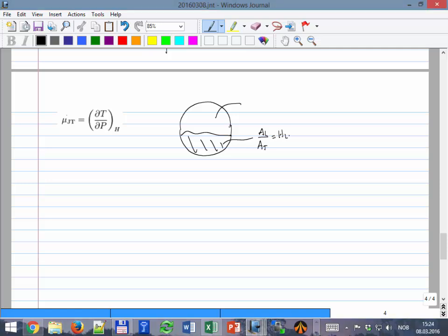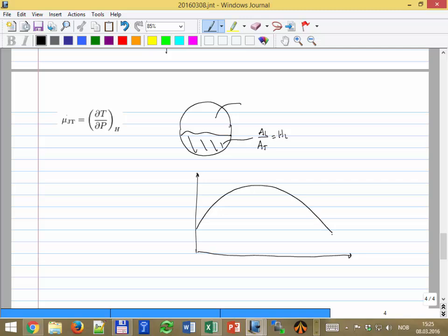So if it's increasing, if it's doing that behavior, it's doing something like this, what could it be indicating? We leave it for the homework, and then you have to explain. You will have to explain anyhow, so better to do it in class. Why might the hold up be increasing? Condensation. Okay, that's one thing. I just have more liquid, and there is liquid coming out of someplace. So maybe what's happening here is condensation.